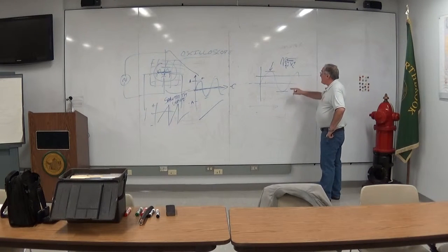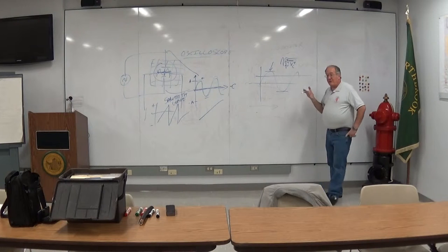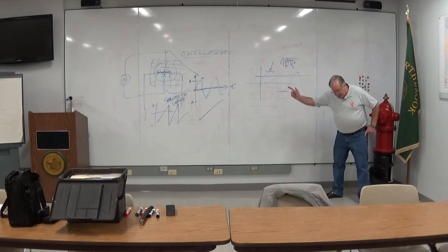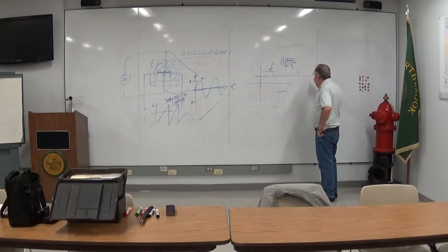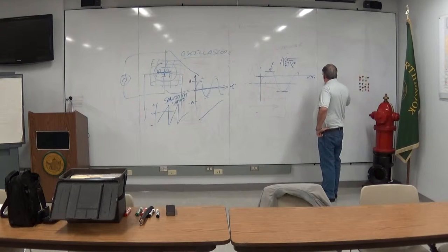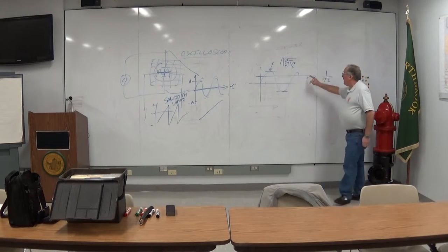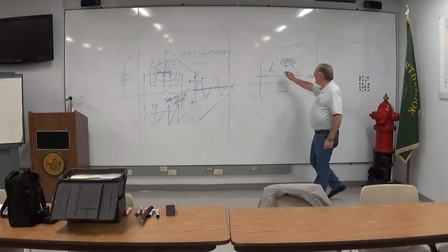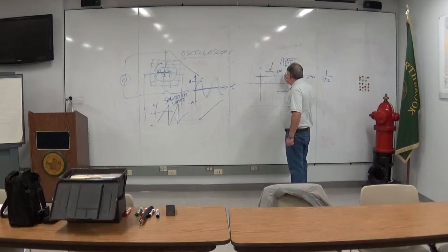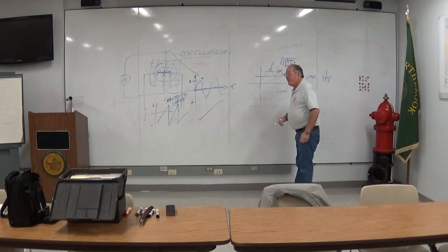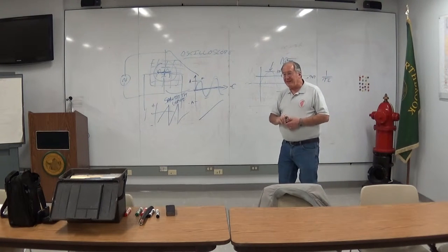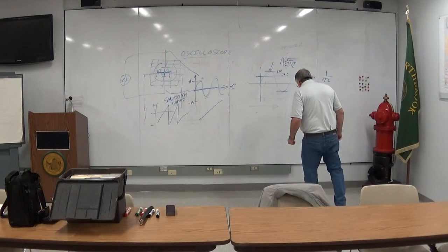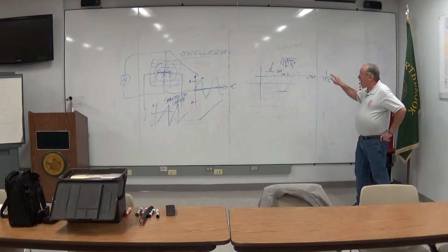And what it really turns out to be is, if this is a sine wave, and most of the time it will be, especially if it's coming out of a wall socket, it will be 0.707, which happens to be 1 over the square root of 2, by the way, of the peak value. So if you had 100 volts here, the DC equivalent would be 70.7. Pay attention, that's going to be on the test if you go for a general and extra class license. That is the conversion between RMS,